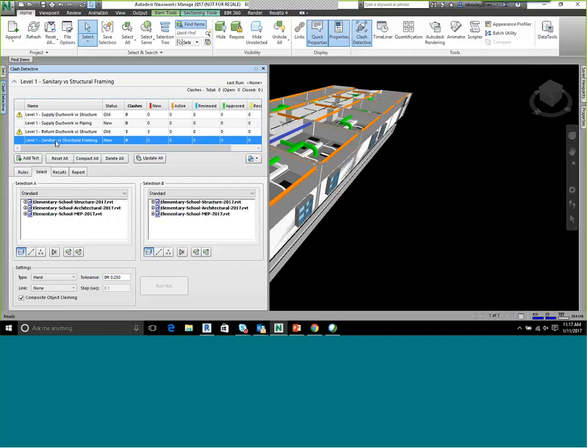All right, so I named my clash something appropriate, something that anybody can navigate. One thing I don't like is don't call it like Nick's clash. I don't really like things with people's names because then people feel like they're not really allowed to use it. Whereas somebody might go in behind you and they might start filtering or sorting through these clashes, adding comments and things like that, which we'll do in a minute. So I created my clash run and I named it.